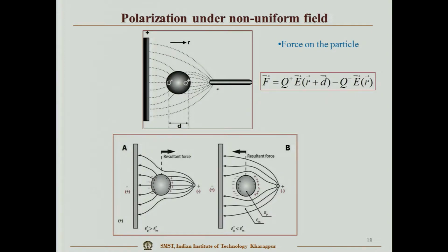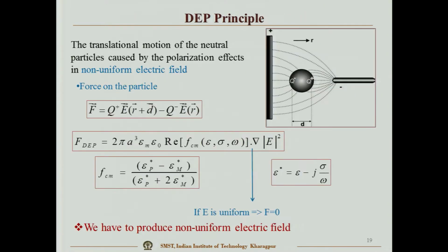It is possible, because this is the equation for the dielectric force. If we consider these things constant, then you have a variation of A. That means you have a larger particle and a smaller particle. For the different particles, different forces will be acting, and accordingly, as the forces are different, they will move in different directions. So, in that way, by the size distribution, you can separate the particles.